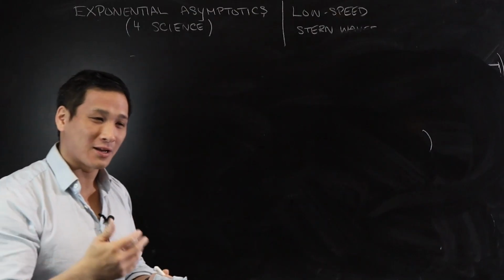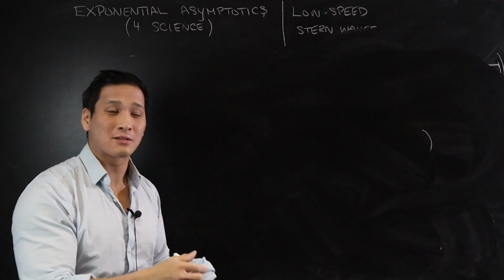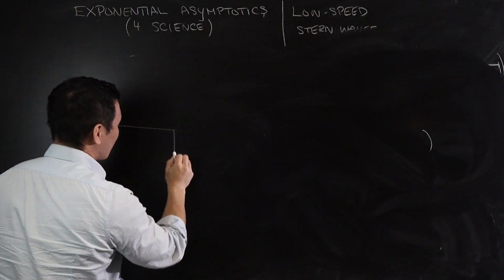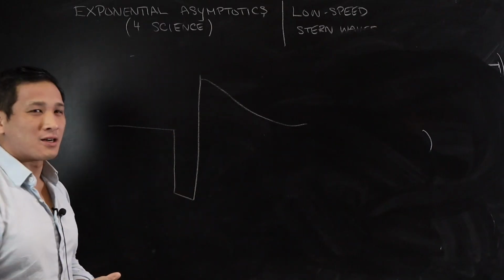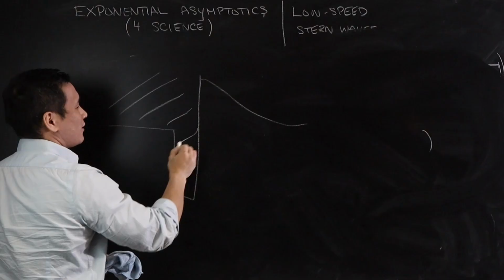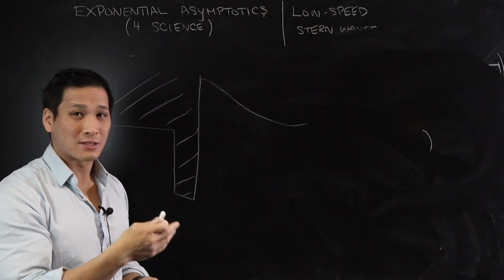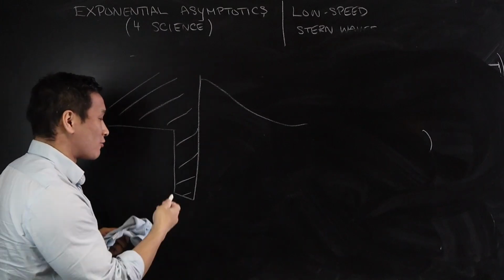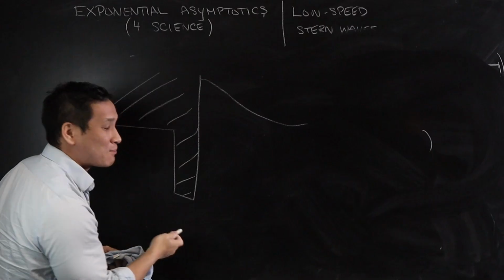Can I make it so that the contribution from one singularity of the ship will cancel with the contribution from another singularity ship? You might argue that, well, actually, because the magnitude of the exponentials that are switched on scales with the distance of the singularity from the main surface, you can reduce the waves by making some kind of obstruction which is deeper and deeper down the flow,